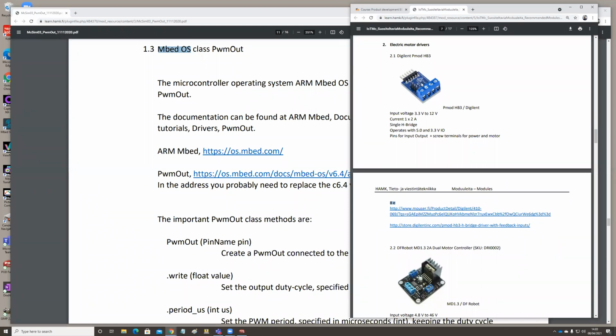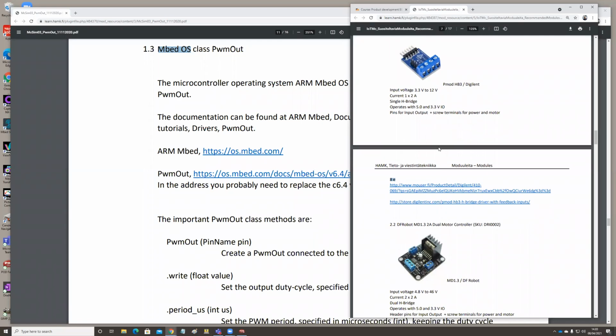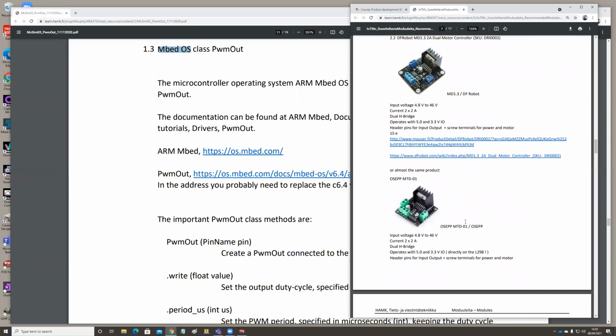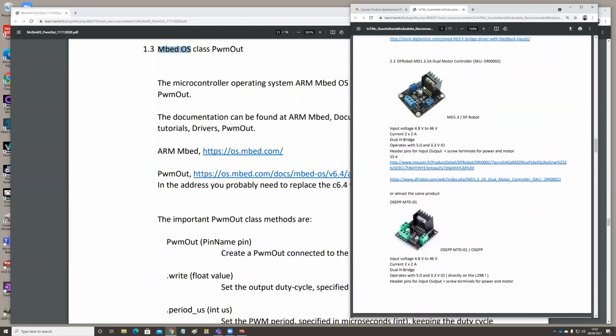The chip there, which is driving the current, is so small that we can't even see it. It's in there anyway. Then this is a little bit more traditional. The driving chip is larger. This is not as modern as that one. So in this one, we can see the motor driver circuit, an integrated chip with the H-bridge driver. And then there is a heat sink, which is dissipating the extra heat. When it is not switching the current with 100% efficiency, it's heating a little bit.